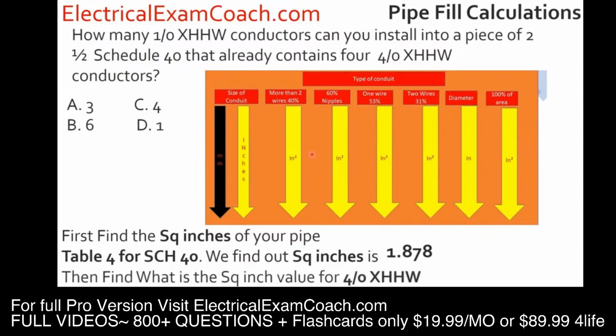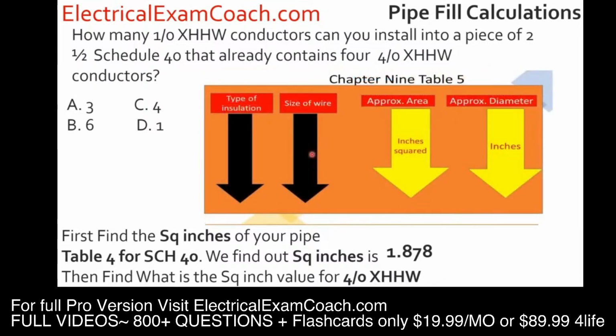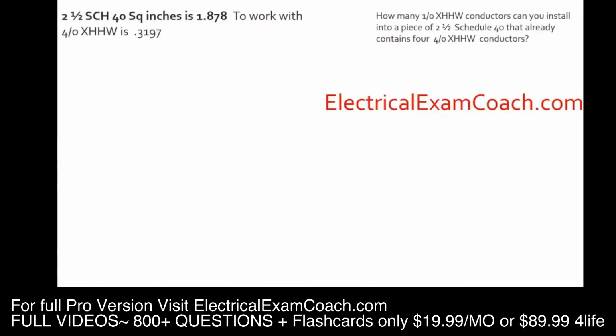Now we need to head to Chapter 9, Table 5 and find the square inch values of our wires. When we get there, we make sure that we're in Chapter 9, Table 5 and not Chapter 9, Table 5A. Coming down the left-hand side for the type of insulation, then finding our wire size, then we come over to the approximate area in square inches, and we find its value. Now that we have our conduit and our starting conductor, let's write down the conductor that we want to install, and it's 1/0 XHHW. Now we can start all over.